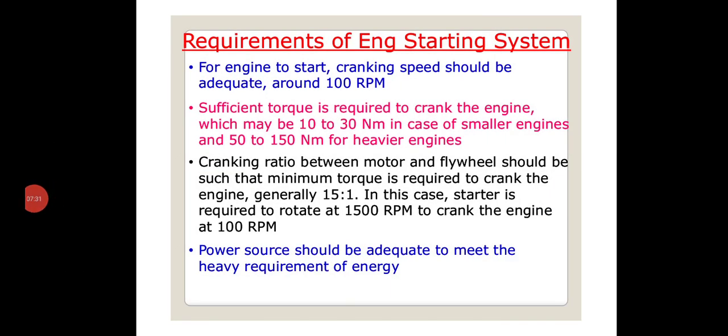Requirements of the engine starting system. The condition of an engine at the time of starting is not conducive for initiation of combustion, since the temperature of the cylinder is too low. Further, at low speed, the time required to complete the suction and compression strokes is relatively higher, due to which heat transfer from the working substance is high, which further lowers the temperature of the working fluid during the compression stroke. Therefore the temperature and the pressure are not sufficient to initiate the combustion.